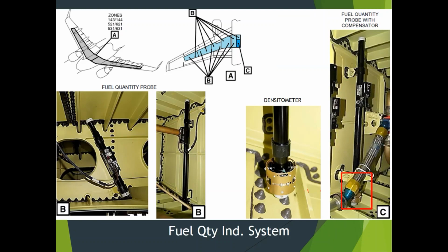Here's the densitometer right here, okay, which is also tied to a probe that's in the right wing. Here's a probe that's sitting straight up and down at the very near the root, very tall, shorter one out in the wing area. You see there's wiring going to them, it's sealed wiring, very low current, low voltage. They're designed not to spark. Essentially, it's just reading a capacitance.